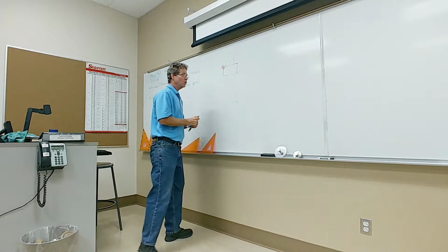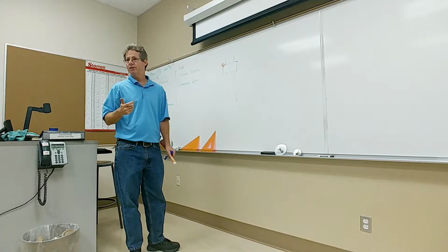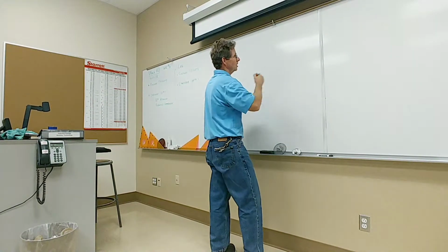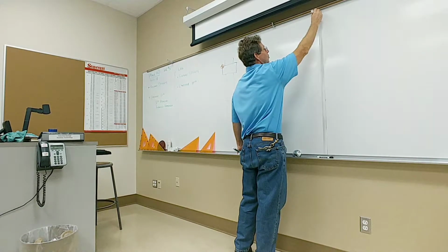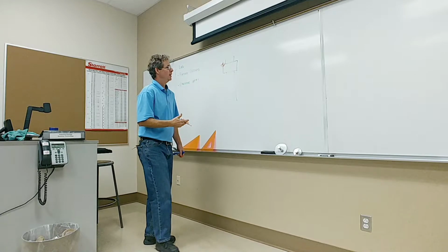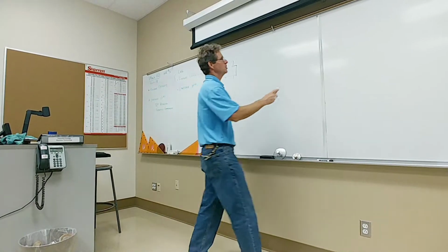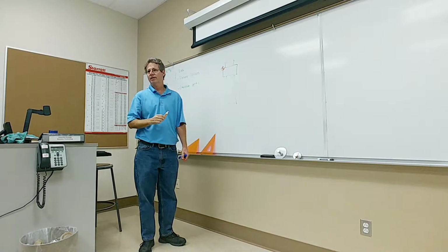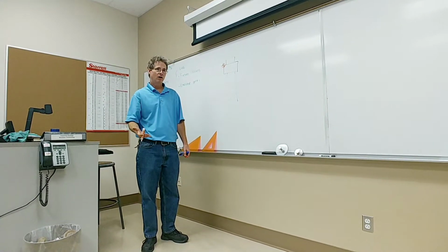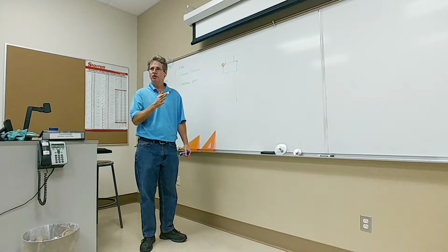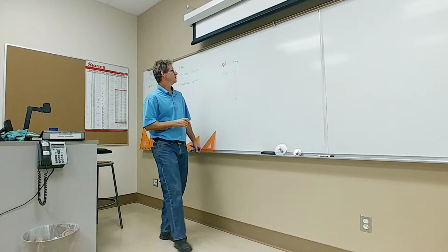And then you would have to make a precision measurement on the machine and measure exactly, like, I just said this half of the whiteboard is my machine travel. Here's my machine 0 coordinate, okay, which on the Haas is pretty much exactly where it is. And it's going to be a precision measurement from that machine 0 position to your part. Okay? So when we program our parts, we always program our parts from a common X0, Y0 position, and Z0 being the face of the part.